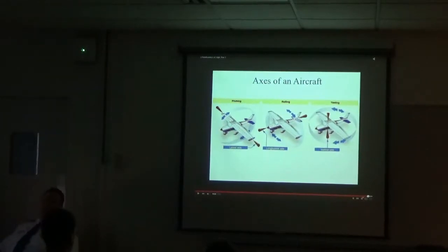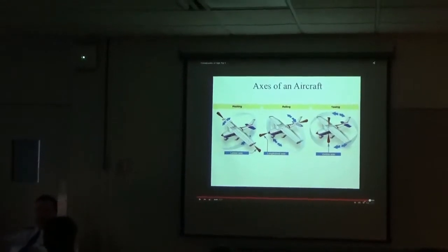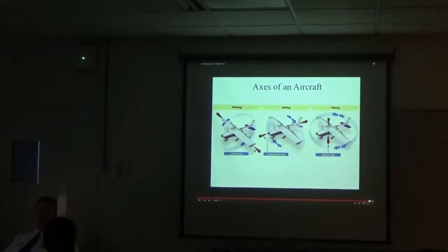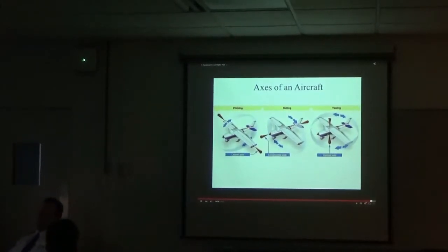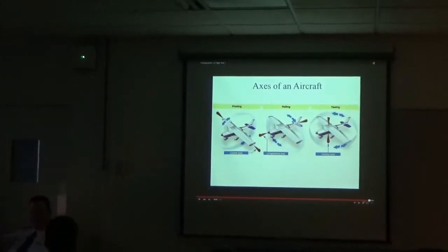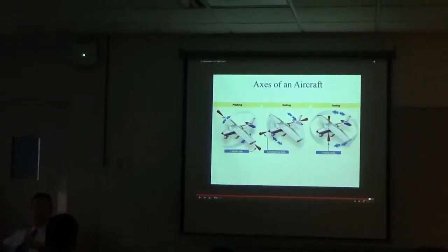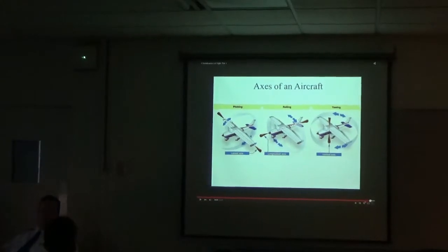The rolling of the aircraft. What controls cause the rolling? Both the outside of the aircraft as well as the actual control you manually use. Anyone? Oh, Scheller? Yeah, Lieutenant Colonel Scheller. The ailerons are what make it actually roll on the outside, and you turn the yoke or the joystick in order to make the ailerons move. Correct. So, the yoke controls two aspects of the aircraft itself. The pitching and the rolling.